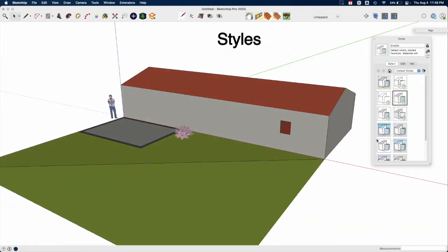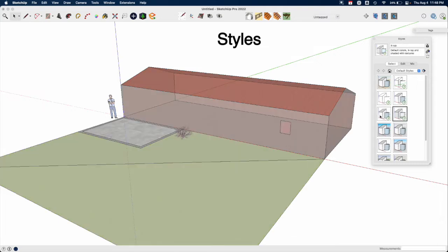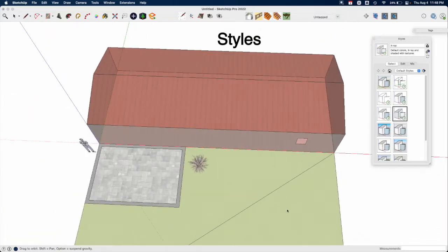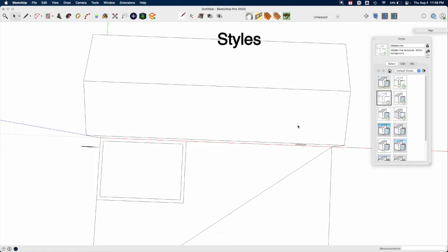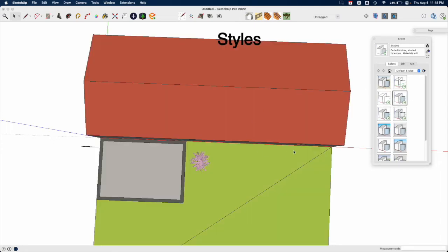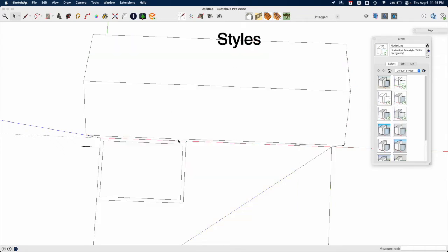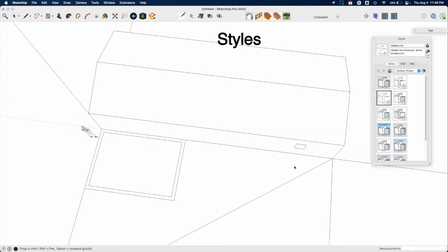We've got a shaded without textures and various different views. We've got an X-ray. The views that I use the most is when I'm doing a top-down plan, I'll use either a hidden line without color or a shaded without textures, because the documents for the specs typically don't need to show the texture pavers, and so it helps just save on detail. It's easier to draw dimensions and make annotations on this. Same with the shaded. So that's what those scenes are used for.